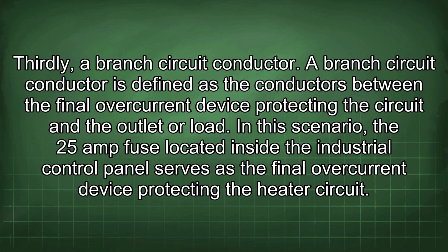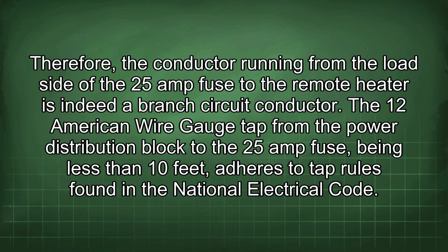Thirdly, a branch circuit conductor. A branch circuit conductor is defined as the conductors between the final overcurrent device protecting the circuit and the outlet or load. In this scenario, the 25 amp fuse located inside the industrial control panel serves as the final overcurrent device protecting the heater circuit. Therefore, the conductor running from the load side of the 25 amp fuse to the remote heater is indeed a